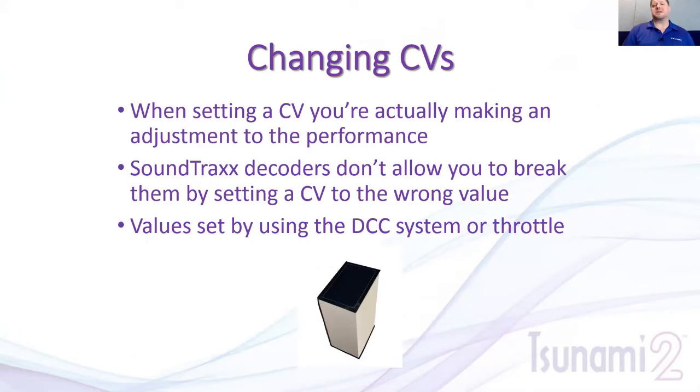This to me is one of the biggest misnomers in DCC, because our engineers write the program on their computer. They tell the decoder how to behave, and then you can select from those choices to find out how to make the decoder behave for you. Which are the choices we give you. So for example, when you're changing the volume on your television, you're essentially doing the same thing. It's just you're using a remote control of some form, or you're using a volume knob. Where in DCC now you have to go in and change CV 128 to a value of 0 to 255. You're not programming the volume, you're just making the change.